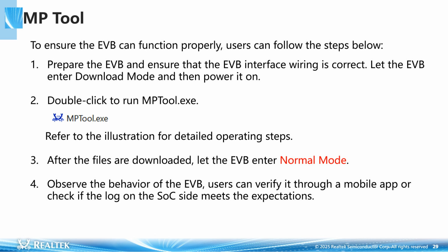3. After the files are downloaded, let the EVB enter normal mode. 4. Observe the behavior of the EVB. Users can verify it through a mobile app or check if the log on the SoC side meets the expectations.